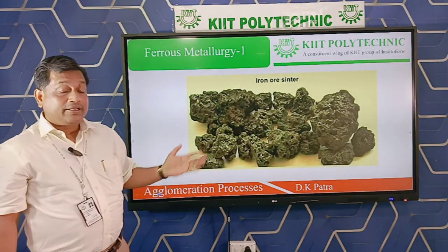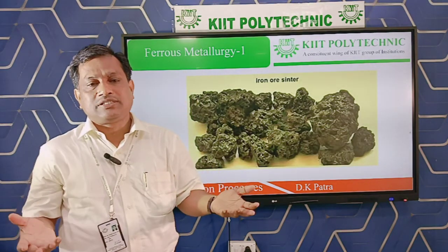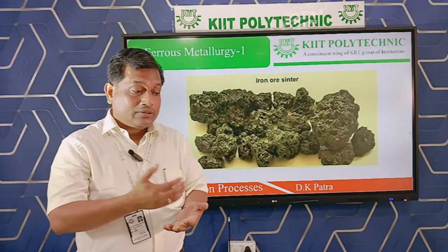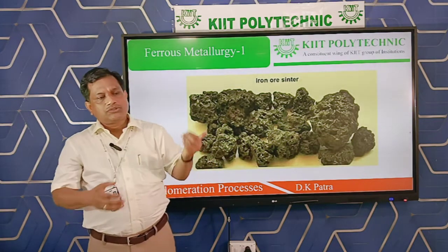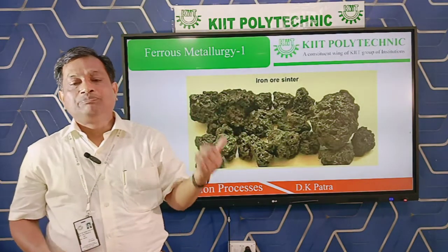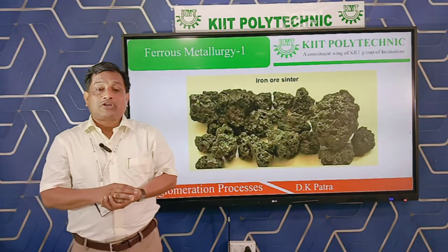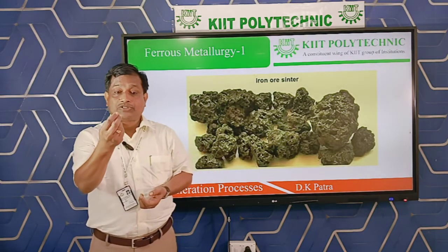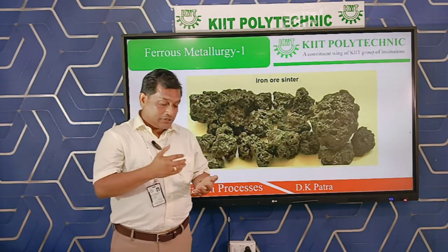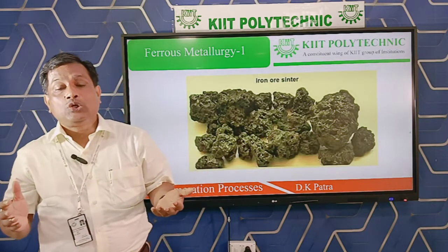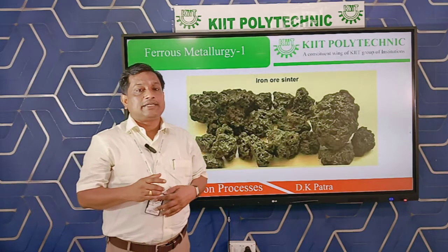This is a very vital process in almost all blast furnaces. We are going to recharge the sinters. Now another question arises. In the beginning step of the sintering, first we collected the iron ore from the mines. We broke it into small pieces, that means we did the crushing operation. After the crushing operation, we collected the small particles of the iron ores. But during this crushing operation, we cannot guarantee that no fines will be generated. Definitely some fines will be generated.